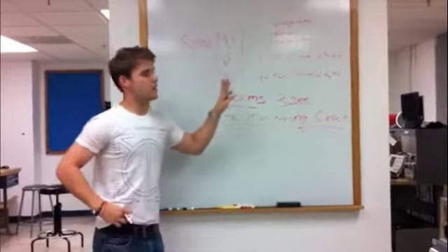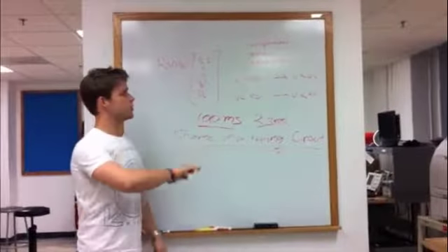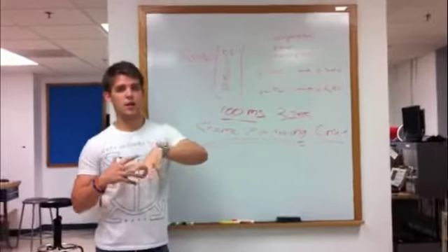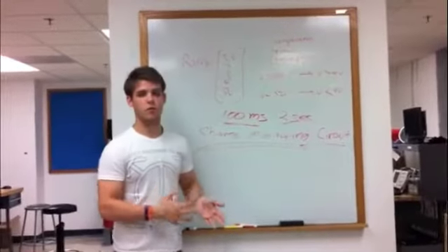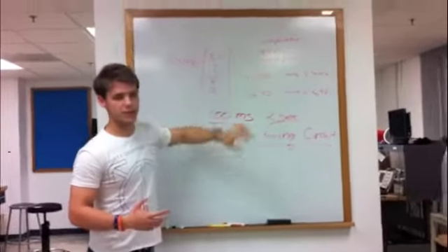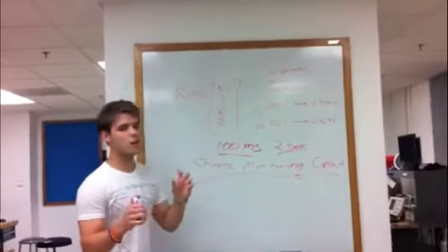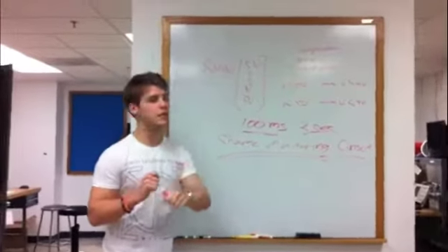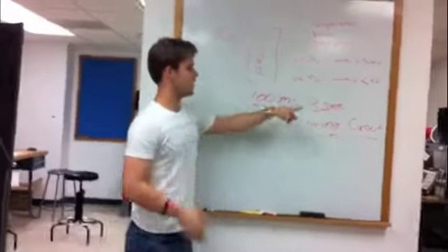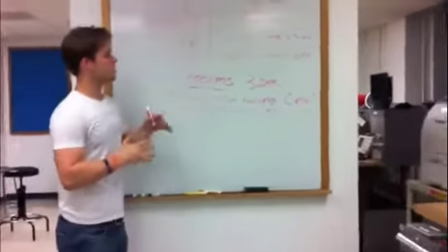So, the basic way that a timer works is that the output of the comparator and the transistor goes into the timer, and so the timer reads what is going on, whether or not it wants the comparator to express if it's over or under 4 volts. So, let's say the timer, for whichever one it reads, okay, it's over 4 volts, I need to express this to the LED. So, we have it set up with resistors and different pins to express that we want it to go for 100 milliseconds every 2 seconds. So, it does that, runs all the way through the timer and into the LED, which is connected to ground.